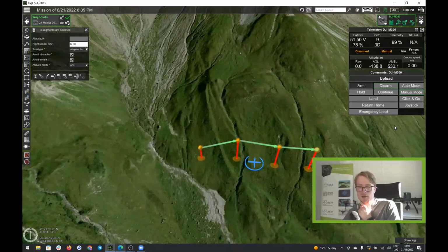Yeah, in case you're struggling with the error that says waypoint exceeding height limit, there are a few ways to check that. Number one is to check our mobile app, because you can also set the maximum height in there. And next, check the drone profile. But I think most likely if you're getting the DJI error, so this looks like it's from the DJI SDK, not from UgCS, then most likely check the app and make sure that you have the maximum altitude set there as well. That it's not set to, for example, 50 meters, but it's set higher instead.